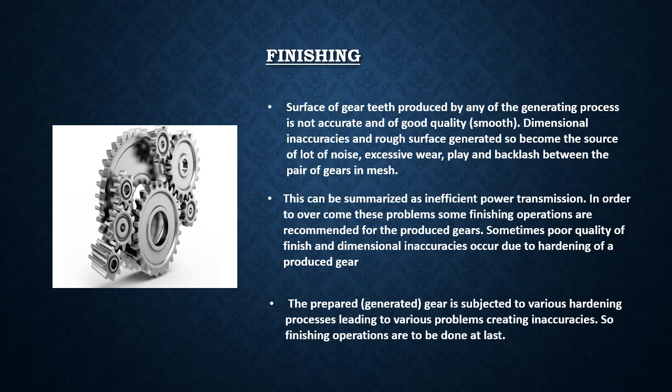Then the last one is the finishing process. Metal can sometimes fill in cracks in a casting mold or spurs. Pouring channels pour the mold, and manufacturers must often finish the casting. Following casting, this can be accomplished through a variety of finishing techniques including sanding, grinding and buffing. Once proper appearance and surface texture has been achieved, further post-treatment processes such as painting or electropainting may be necessary for some applications.